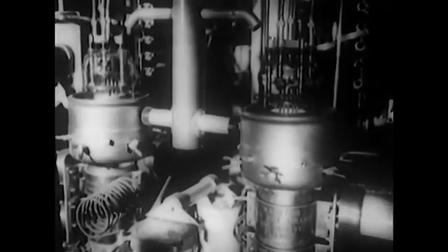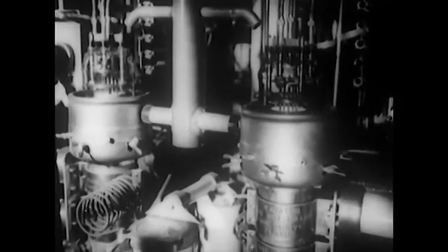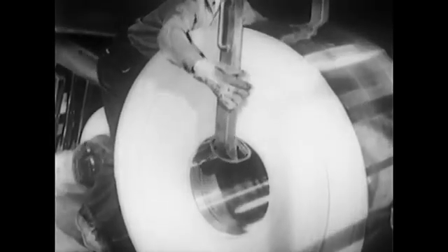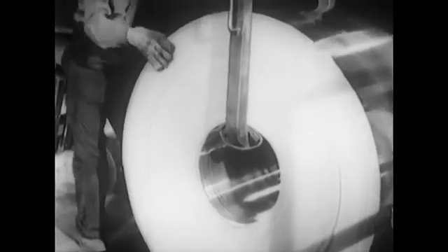If you look closely, you can see the difference in texture between the porous tin entering the top of the coil and the shiny flowed tin leaving at its base. And these are the tubes that generate the high-frequency current which makes the entire process possible. Another important result of this new Westinghouse electronic process is time saving. Tin can now be flowed at a rate of more than 1,000 feet a minute.